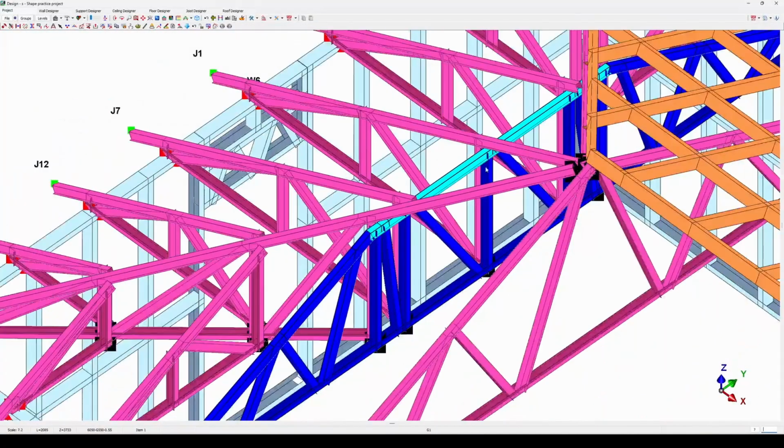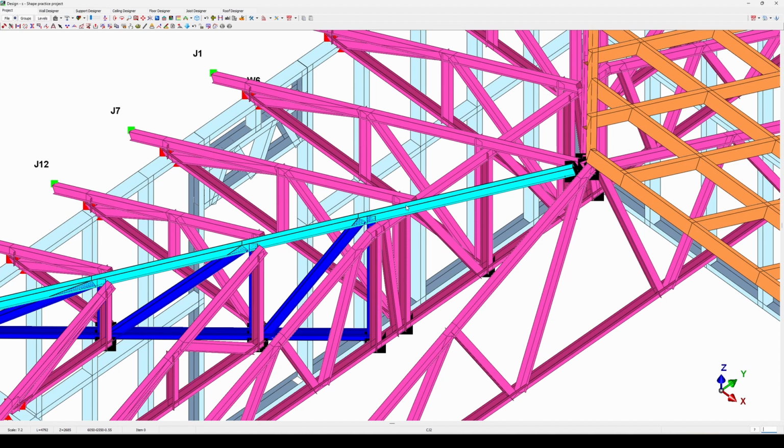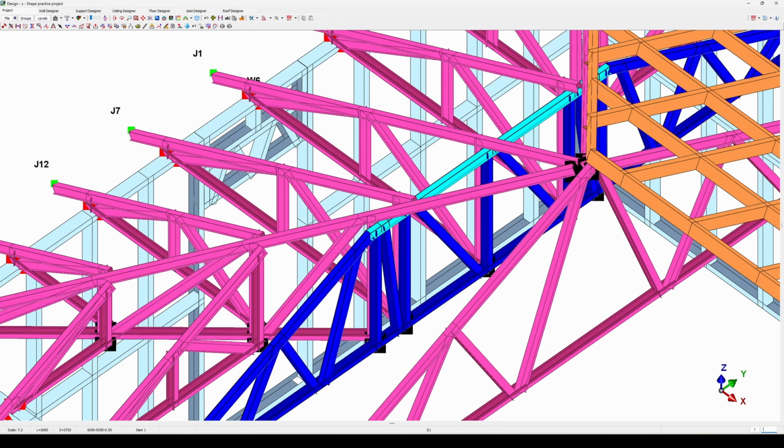You can see this girder truss right there on the top chord has a lower height than the actual roof profile. This allows for the jack and the corner jack top chords to extend across and fully complete that roof structure to allow for the purlin connection. We also call this a truncated truss in some aspects as well.